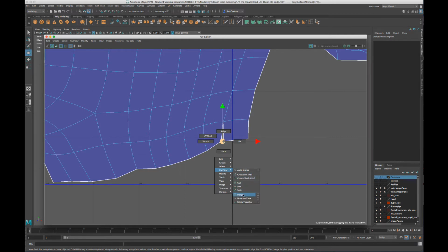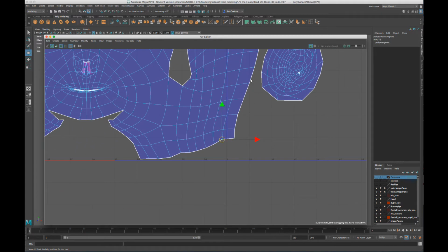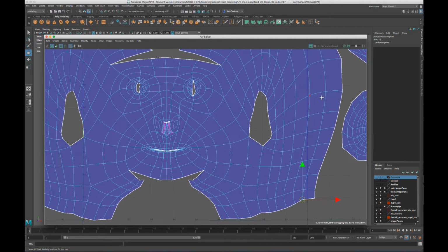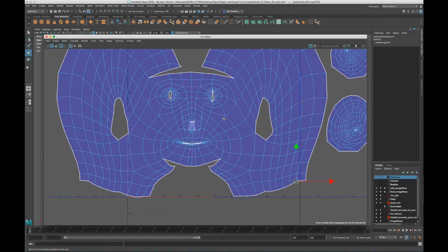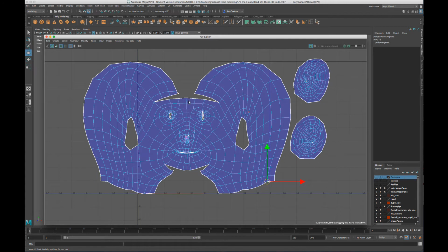Just on a cut sew, click merge, and those two become one. Any little splits there, you can merge edges in the UV, you can merge CVs. Really, you're merging UVs and combining UV shells when you do that, making one larger continuous piece of fabric, as it were.